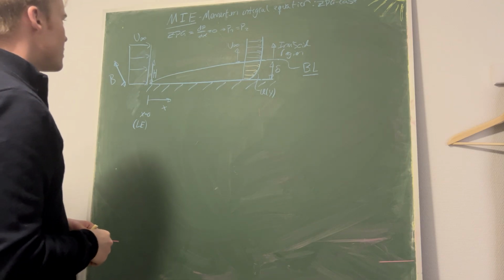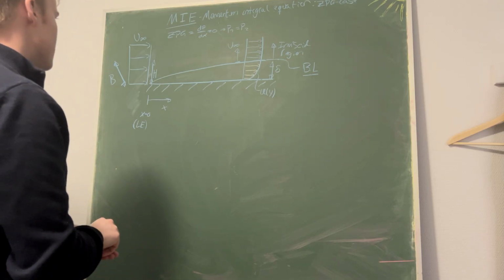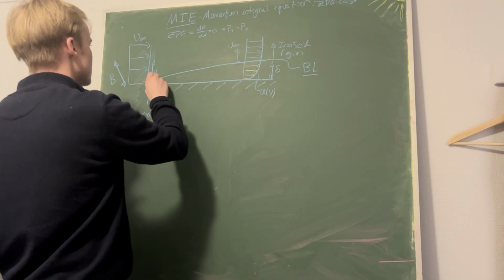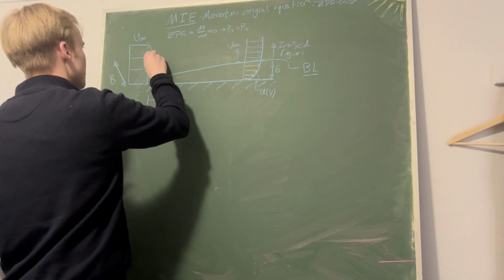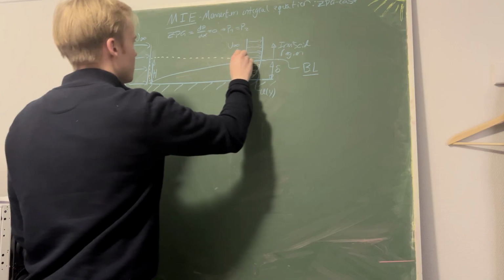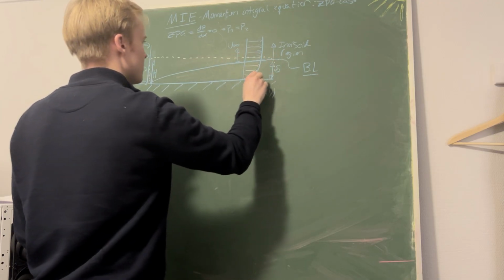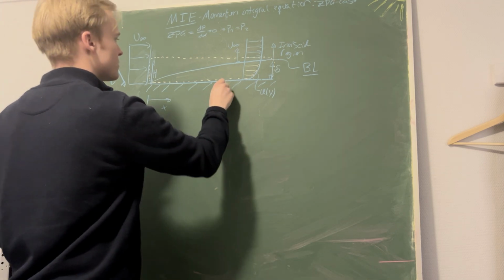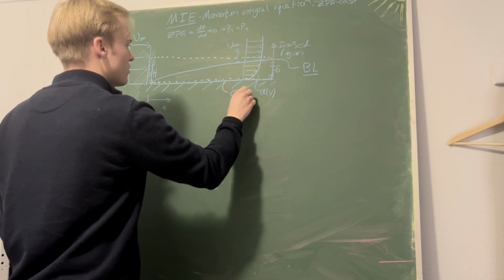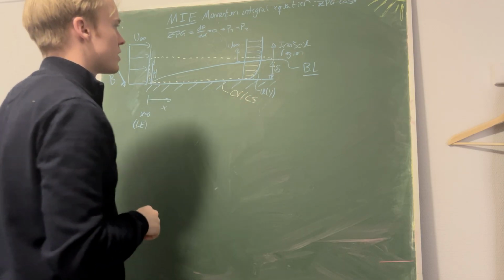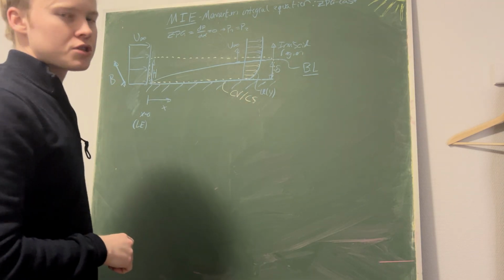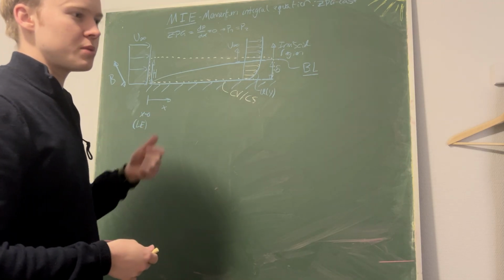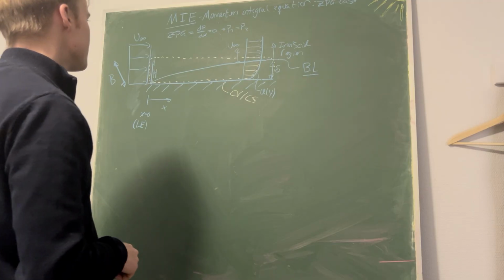Okay, and then we could draw our control volume box around this. So if we draw this, right, this is our control volume, CV or CS, depends on how you look at it. We will consider a control surface because it's what moves in and what moves out, which defines what is happening inside the box, right?